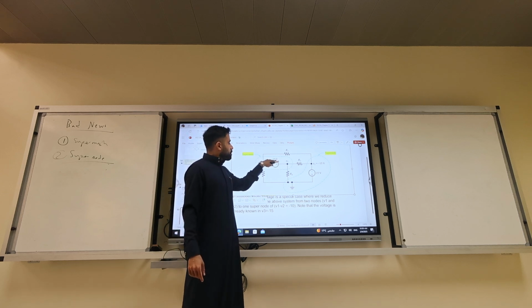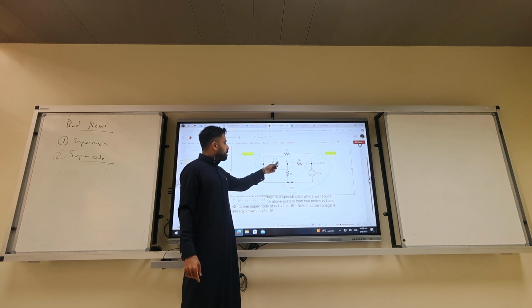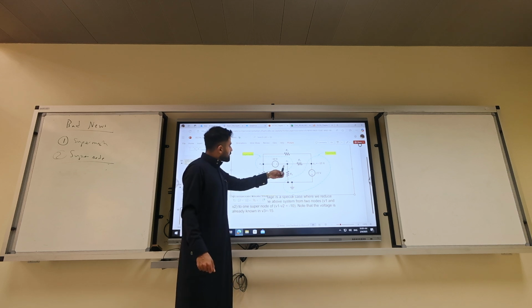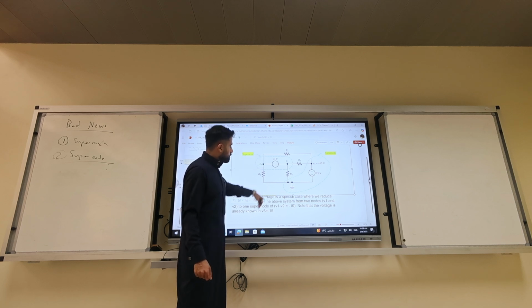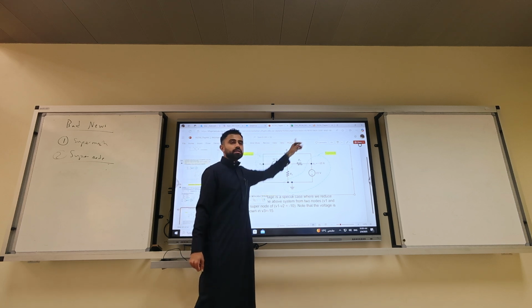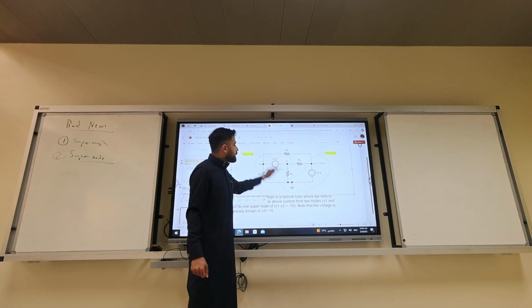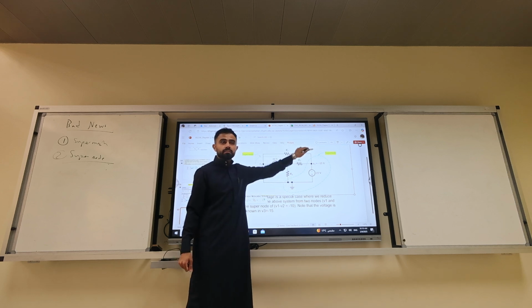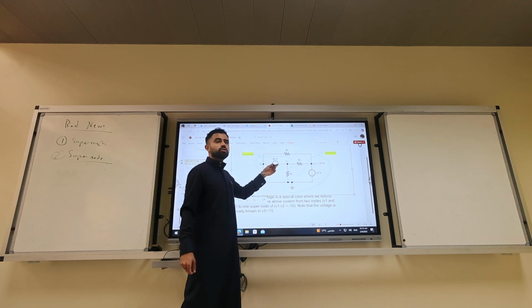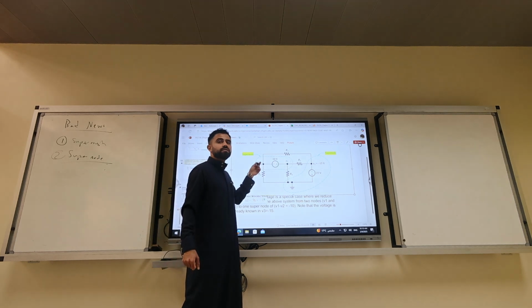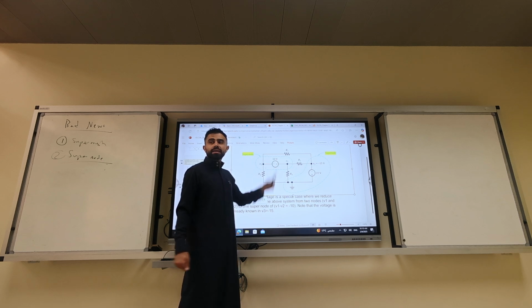Now, because right now you cannot calculate the current that moves from V2 to V1, there's no resistance here. We say let's create a big supernode and write KCL, 1, 2, 3 currents, IA, IB, IC. Equation 1. Equation 2, V1 minus V2 equal to minus 10, or you can say V2 minus V1 equal 10, right, Hatem?